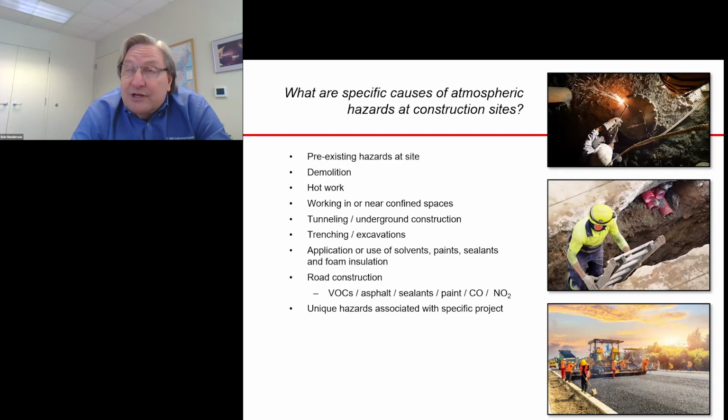A lot of times, if that is an industrial site, you have the after effects of what went on beforehand. So always be cognizant, always be aware of what that site was being used for before you turned up. Pre-existing hazards can get you in a lot of trouble. If you have demolition going on or hot work going on, you have introduced additional hazards on top of what other hazards might be present.